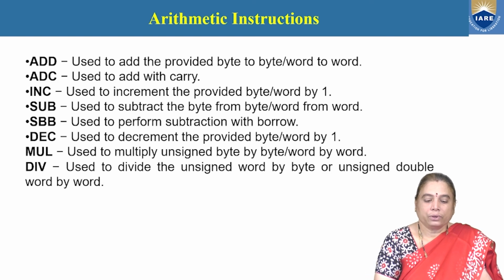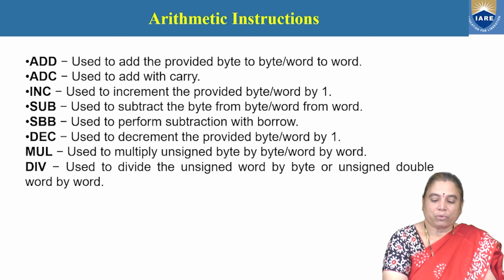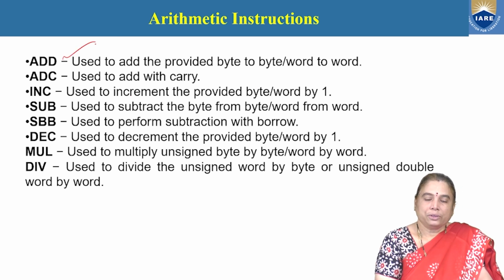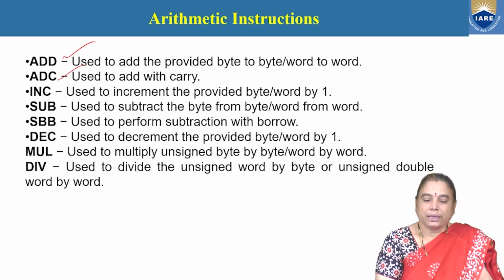Next variety of instructions are arithmetic instructions. The arithmetic instructions facilitate the computational capacity. So here numerous instructions can be used. The ADD instruction is used to provide addition. ADC is addition operation along with carry. INC means increment operation. The specified register content can be incremented by 1.